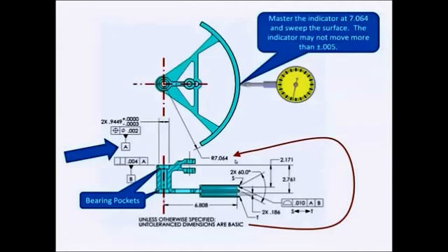What could be simpler, and why wouldn't you do it this way? Because it only has one meaning, especially since this can affect life and limb. The entire shape of the end of the throttle pulley sector with the V-grooves could easily be checked with a simple fixture and an optical comparator. Next time, I think I'll take the bus.